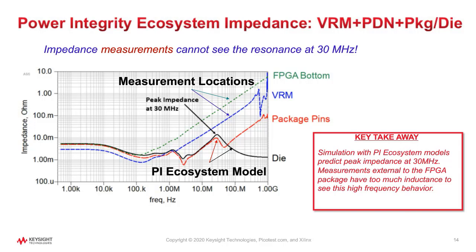Here we can see the challenge. Voltage noise ripple is impedance times the dynamic current, or the dI/dt. But what is the real dynamic switching current? Is there a vendor model that predicts it? Or is it possible to measure this elusive dynamic switching current?